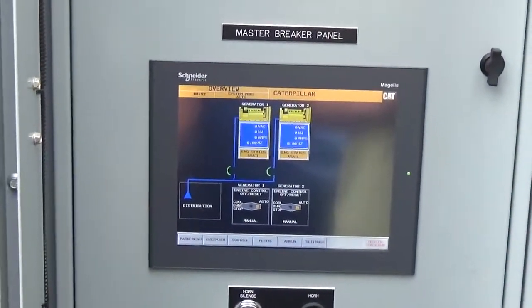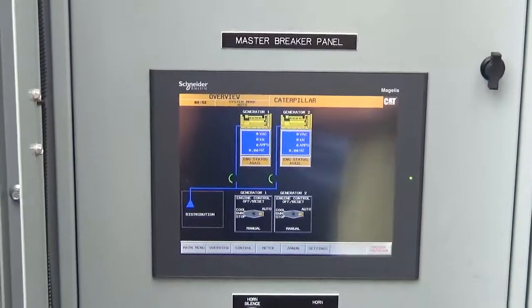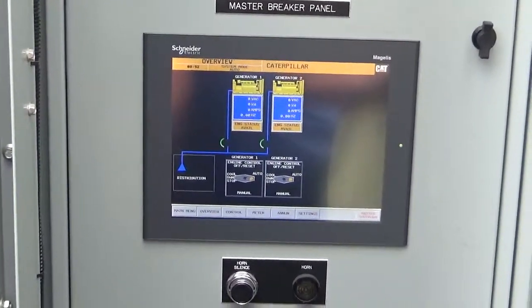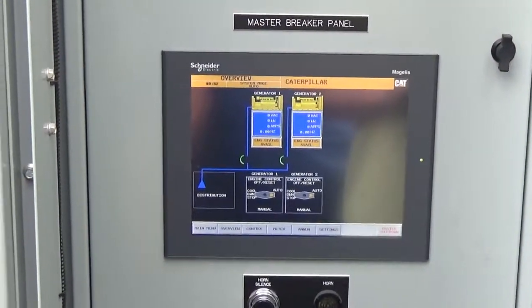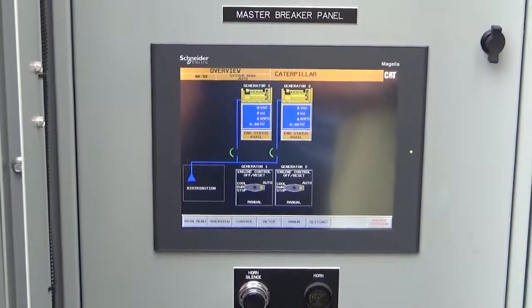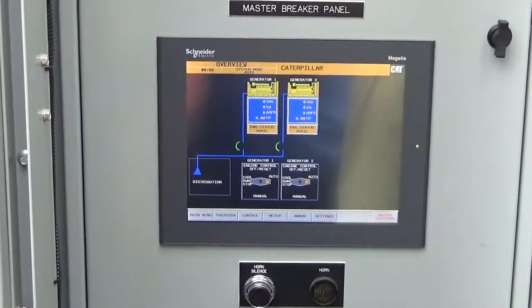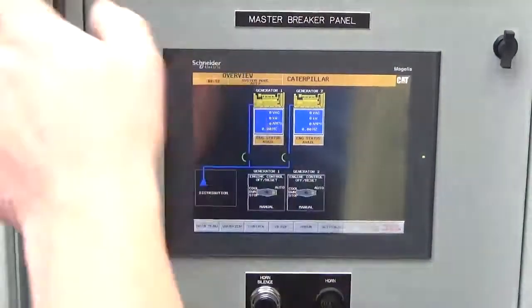If you don't acknowledge it, the light continues to blink. The condition will go away, and you'll come up and it'll be a blinking light, and you don't have any idea what it is. It's not an alarm. But with the switchgear, if the condition is gone, the switchgear doesn't see it anymore. You only see it at the generator.